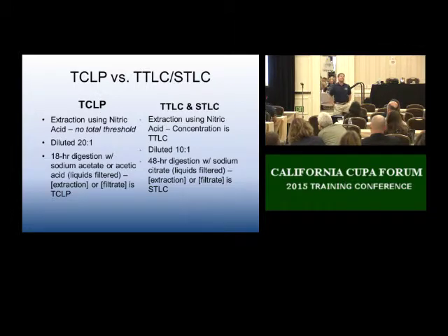If I read Appendix 10 and look at SW-846, it tells you what a free liquid is. I use a 70 micron mesh screen used in the paint filter industry, and I put a 5 cc sample of my waste in it at 1 atmosphere at 78 degrees Fahrenheit, and you wait 5 minutes. And if there's a drip that comes out at the bottom, that is considered a free liquid. And if it doesn't drip within 5 minutes, your sludge does not have a free liquid, nor could it be ignitable based on this criteria, because this criteria is based on a free liquid. Is everyone with me? Okay.